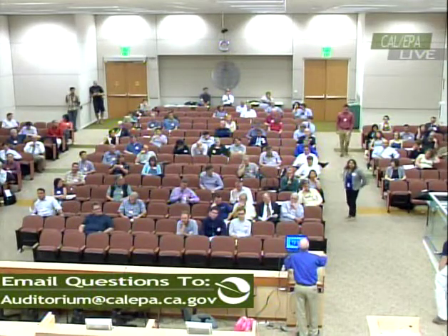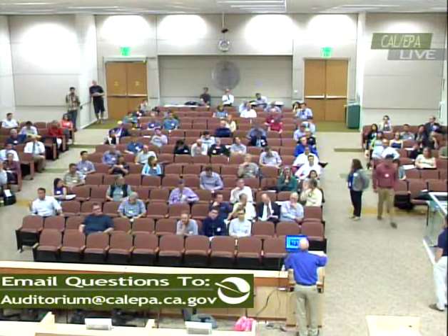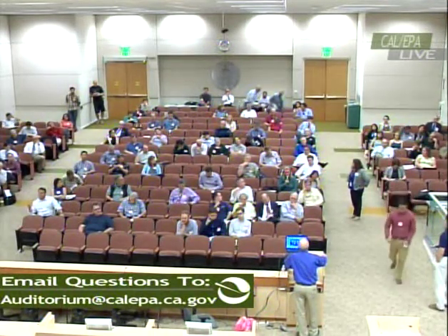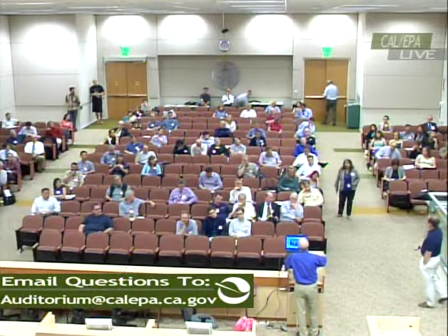Thank you. Mindy Boley with the City of Vacaville. I was just wondering, you had a non-detect on the perchlorate and the hex chrome. What were the levels to begin with before the treatment? Okay. Hex chrome was bouncing somewhere around 25 to 40 parts per billion. Perchlorate was running anywhere from 250 to 600 parts per billion.